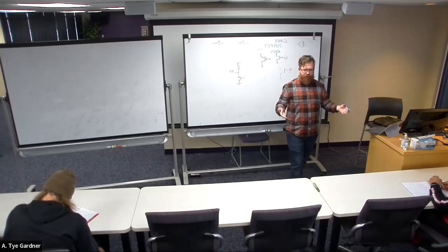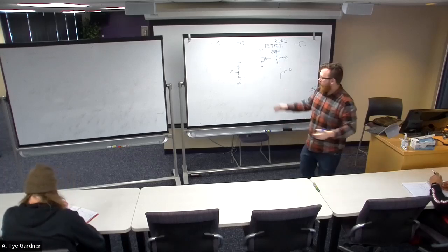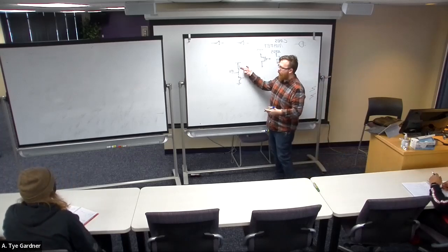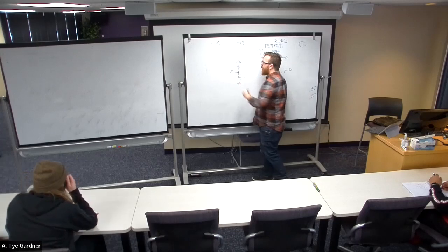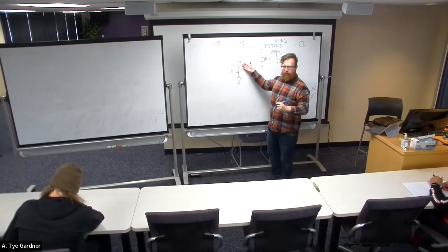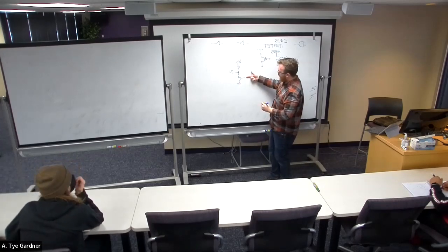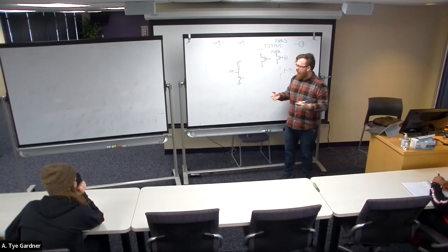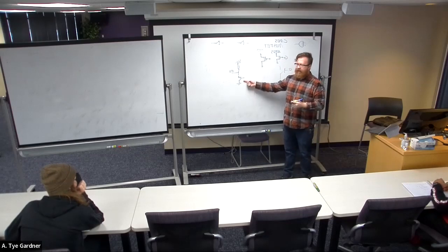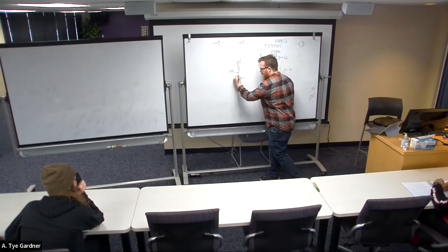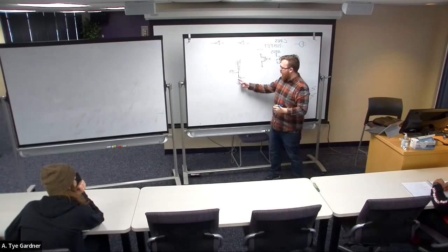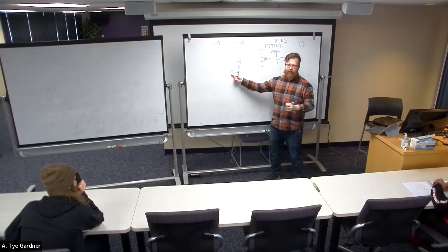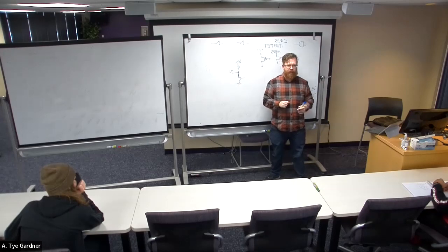The gate is not closed, current cannot flow, it's broken the connection. I have the pull-up resistor to VCC, and I get a 1. A 0 here makes a 1 at the output. I built an inverter, right? If I put a 1 here, the gate closes, it is connected, and now there's a direct connection through the switch to ground. The digital signal is 0. It's an inverter.